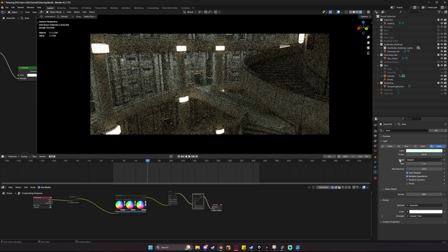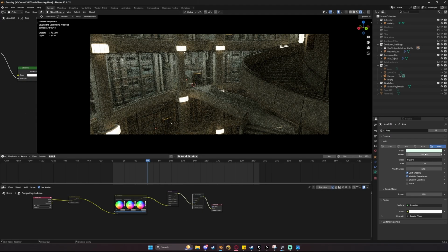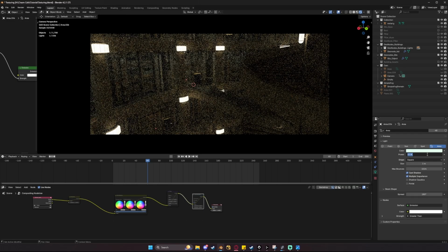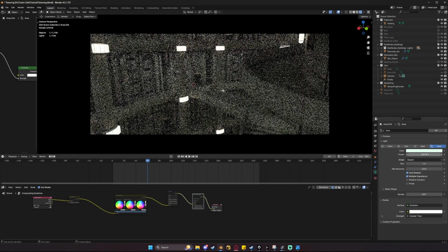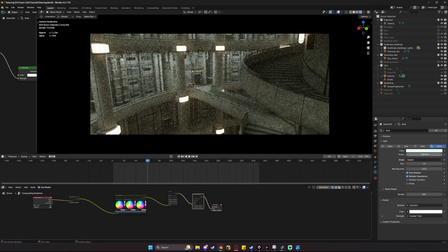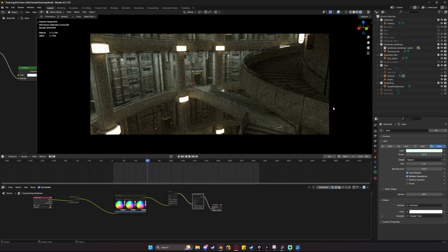All I did was look through my original scene with my lights turned on, and I tried to just eyeball what I felt was a realistic value. For me, this ended up being anywhere between 50 and 100, and I found 60 to be a nice value. That's 10, not 100 there. If we push it all the way to 100, it feels a little too bright for me, so 60 really did end up being the magic number for me in this instance.